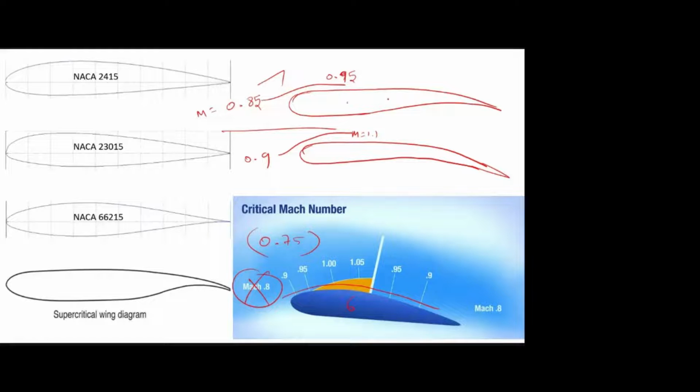That's why in commercial aircraft we use supercritical airfoils, while the 4 series, 5 series and 6 series are used only for smaller and medium range transport aircraft. Mostly for the 4 series, the maximum cruising speed will be Mach number 0.5. This is more or less the same for the 5 series, and for the 6 series it may be up to 0.6 or 0.65 Mach number, and this supercritical one may reach 0.8 or 0.85. Within 0.7 to 0.8, it can work.